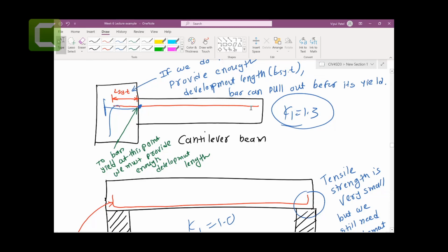If you think of a cantilever, if it is bent, the top portions will be in tension. Concrete is very bad in tension, therefore we put the rebar at the top of this one. So look at the top of this one. Standards want you to make sure this is not good. This is not good, meaning that these bars from here can easily pull out because it's very severe here. You can see they develop very high stresses here. These bars want to come out very easily. So standards want you to stop doing that.